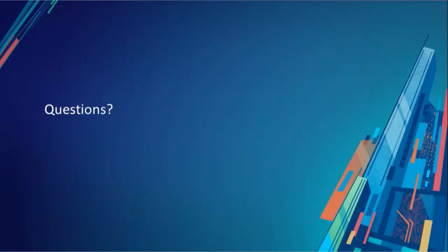The next question is from John. Can you bring in a published feature service for reference for flight planning or a shapefile? Yeah, there are a couple of ways to do this. When you're creating a project within the SiteScan application, you have the option to upload KML files, shapefiles, or PDF files that can be used in the field to create those flight plans. When you're pulling the flight plan up on your iPad, you can turn on those overlays and see them as you're planning. Another way is to connect your SiteScan flight planning app to your ArcGIS Online account. Anything that you have in ArcGIS Online, 2D or 3D, whether imagery, points, or polygons, you can pull in and plan your flight that way.